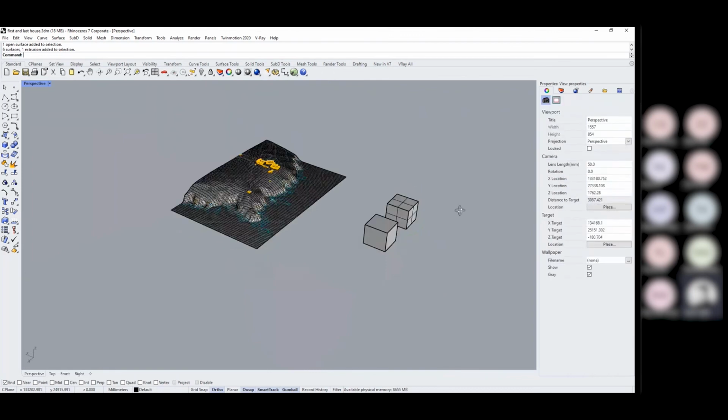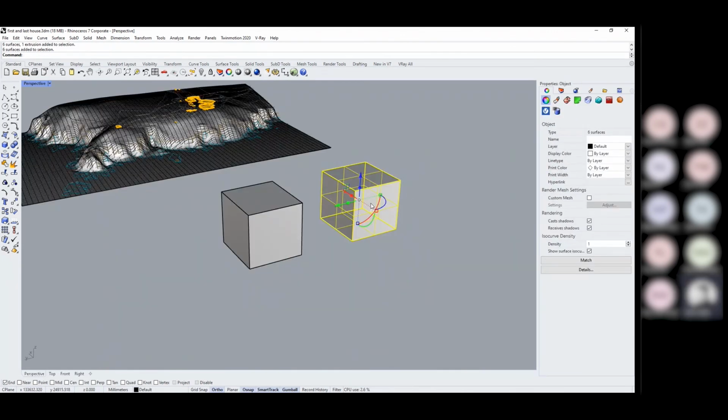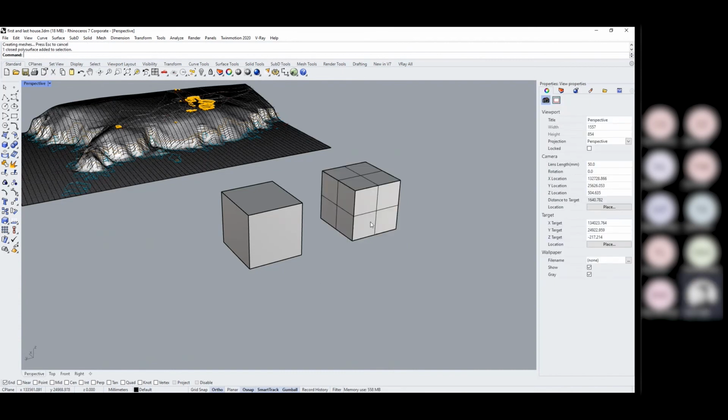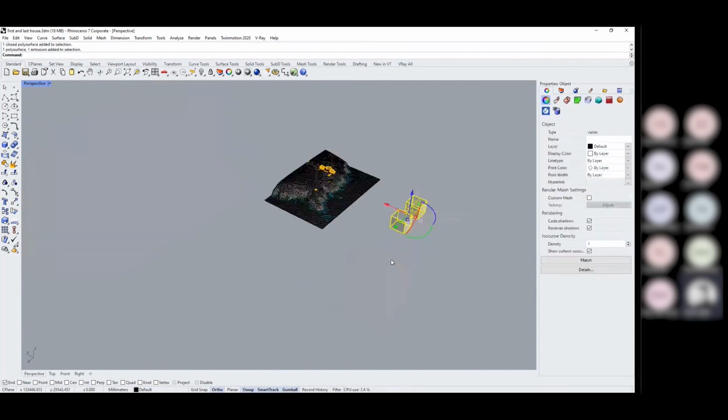So there are ways around it. Easiest way is just to join. So for instance, if I've got all the faces there, I can select them, type the command join, hit enter, and now when I select it, you see it's a closed solid poly surface. Keyword there being closed, meaning watertight. So I could now 3D print those blocks.